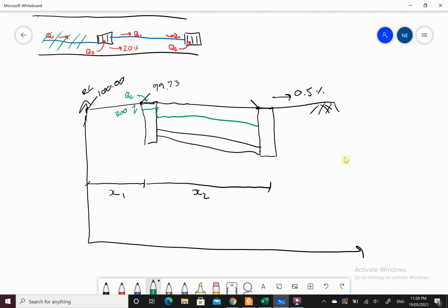We know this point here based on our shock loss K factor. We look at our friction loss and we can work out this point here. All right, this is due to friction in this length. It then runs straight across in our pit. We get shock loss again and the cycle continues.